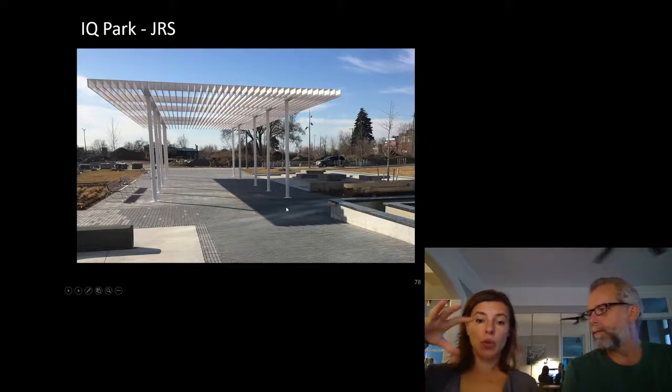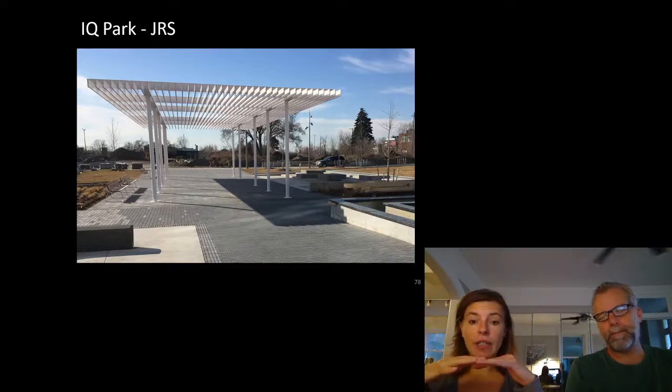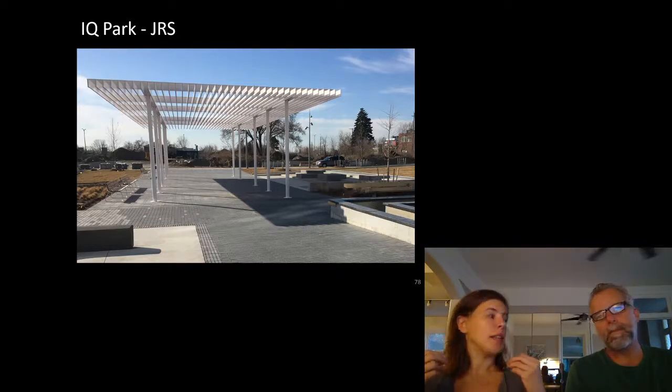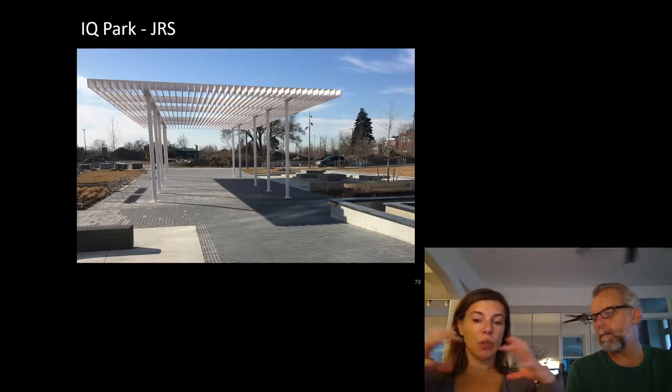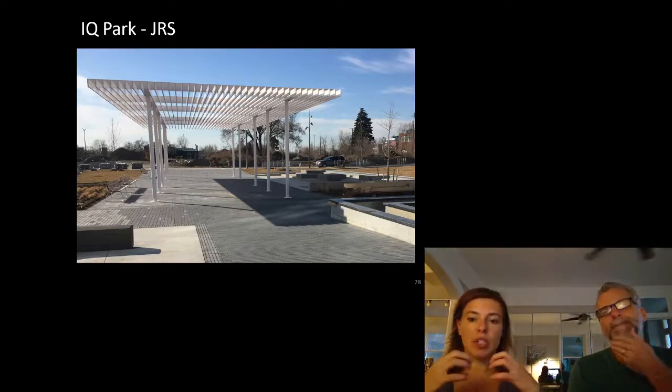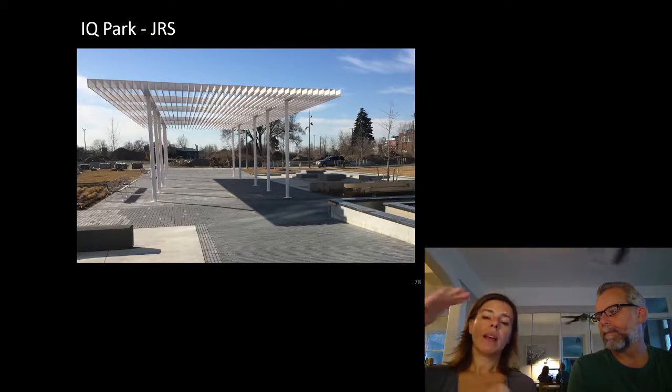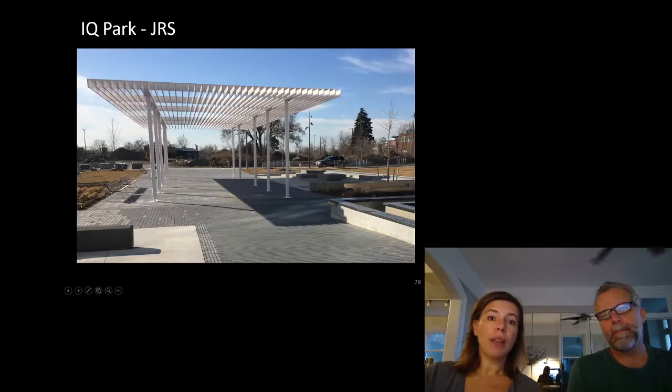I allowed them to keep the top of their concrete below grade and set the pier down. The base plate was designed to take into account that it could be in a rusting condition, so it was oversized. They had to protect the elements, and then they filled that zone with free draining material so it wouldn't clump. We didn't just put dirt there; we kept free draining elements around it so that if water did get there, it would tend to drain away. And then they put their finishes on top, and then a cover plate, more just to hide the rough edges of the brick.